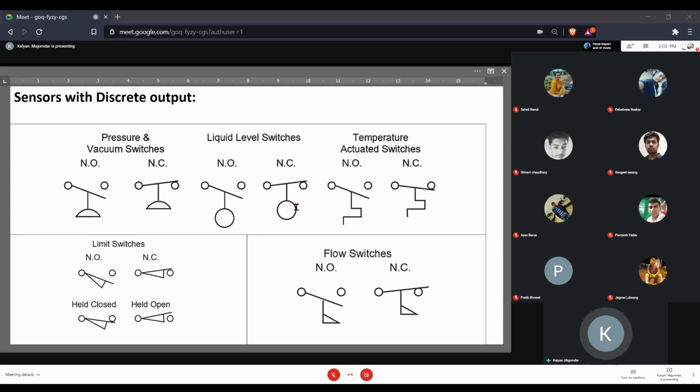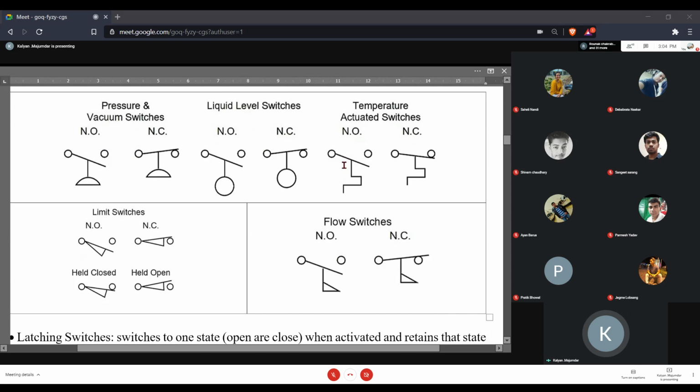And depending upon the state of the switch, the compressor of the refrigerator, the compressor of your air conditioner either operates or does not operate. So that's an example of a temperature switch that you've got in your houses. So these are all switches or sensors which are activated not manually but by physical variables, but behave exactly the same way as momentary switches or push buttons, only that the activation is different. It's by a physical variable, it's not manual. We'll be using all of these in our subsequent programs in our ladder diagrams when we use PLC concepts.